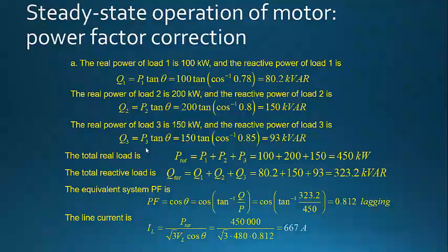Okay, and we know that when a synchronous motor is operating at a leading power factor, it rather generates reactive power. Okay, when it's lagging, it consumes reactive power. When it's leading, it's generating reactive power. And when I say it's generating reactive power, it means that it's consuming a negative reactive power. We made mention of this in our previous lecture. Okay, so take note of that. When it is consuming, it's consuming a positive reactive power. When it is generating under leading condition, it's consuming a negative reactive power. So take note of that.